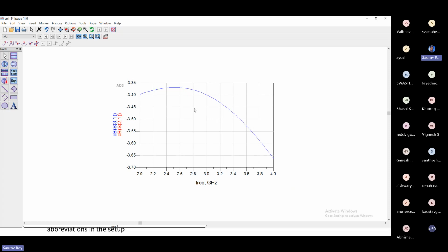What do you see here? Both the results, if you input at port 1, what you will get at port 2 or 3. Both of them are within 3 dB, plus minus 0.5 dB variation. Although because the scale is small, it looks like a big variation, if you see the values here, it is only between 0.3 to 0.7. That is what you will get practically. So it is very close to minus 3 dB.